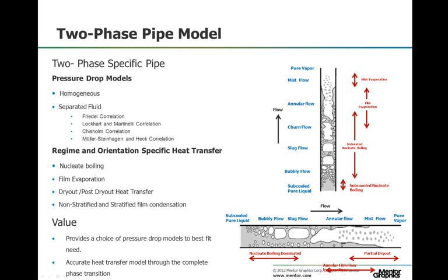The second approach is the separated flow approach. The separated mixture approach assumes the liquid and vapor phases are separate into two streams, each flowing in its own pipe, therefore allowing single-phase assumptions to be applied. The area of these pipes is proportional to the void fraction. This approach has the advantage that it does not have the assumption that the vapor and liquid portions have the same velocities.